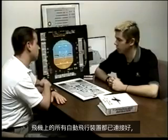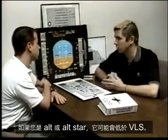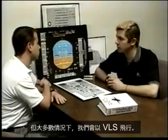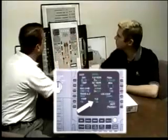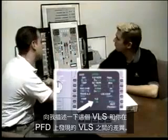No, the aircraft, with all the auto flights hooked up and everything, will slow to VLS. If you're in alt or alt star, it could go below VLS, but for most cases, we'd be flying at VLS. The VLS that you find on your performance approach page on the MCDU is in green. Describe to me the difference between this VLS and the VLS you find on your PFD.